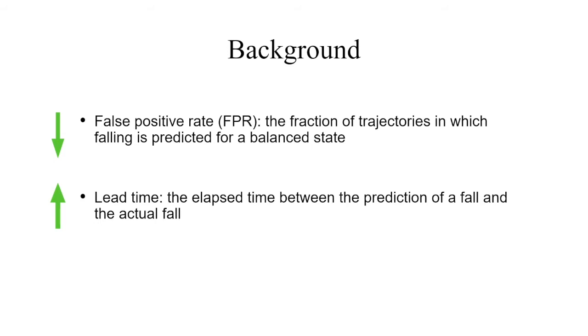Another concept is lead time. It measures the elapsed time between the prediction of the fall and the actual fall. The desired lead time should be as long as the fall time. Once a force is applied on the robot that is deemed to eventually lead to a fall, the fall predictor should raise the alert. That's the ideal case.